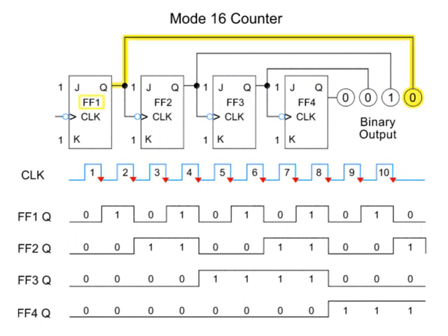The 1's position, or A, must change its state on every count. Thus, flip-flop 1 must toggle for each clock pulse. The 2's position will change its state half as often as the 1's position. Thus, flip-flop 2 will only toggle half as much as flip-flop 1.